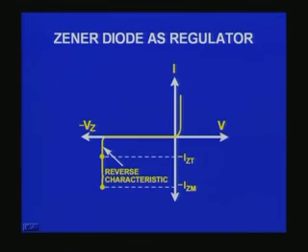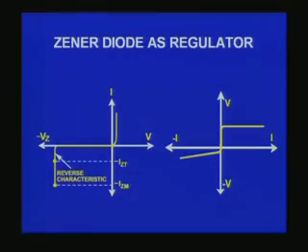The reverse characteristic suggests to us that after the breakdown, the voltage remains constant for very large changes in current. So, this is what we wanted with reference to regulation. You can immediately see how a Zener diode perhaps can be a solution for regulating an unregulated power supply. To bring things much clearer, I have rotated this for some convenience. In this way, you would find, irrespective of the increase in current, the voltage remains constant.